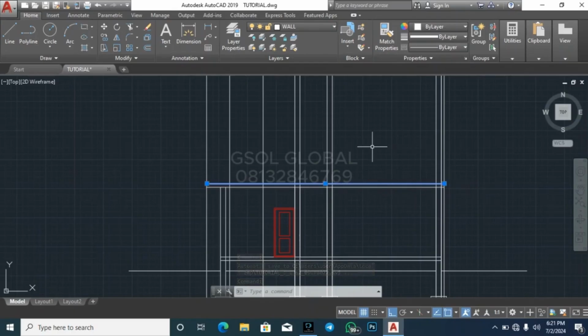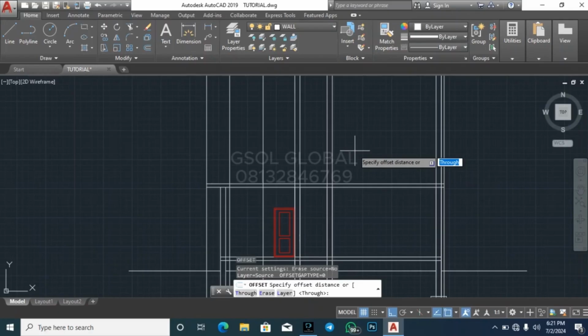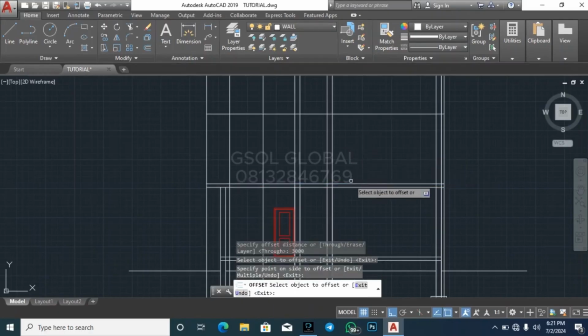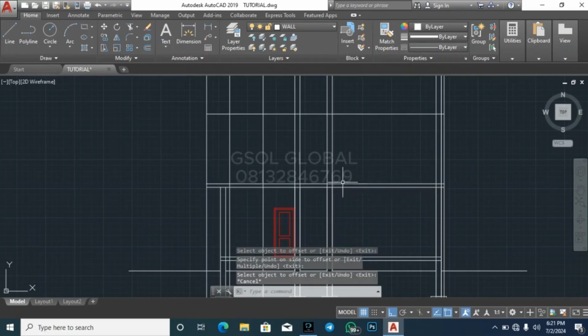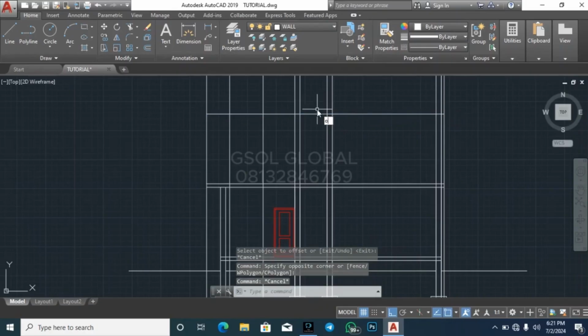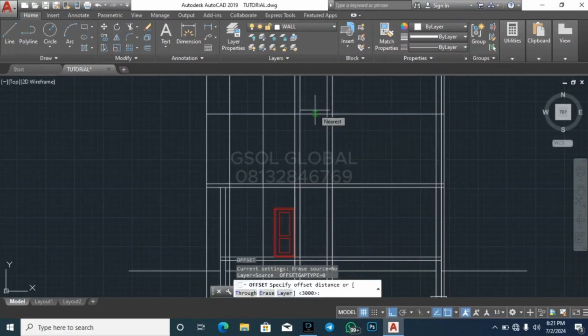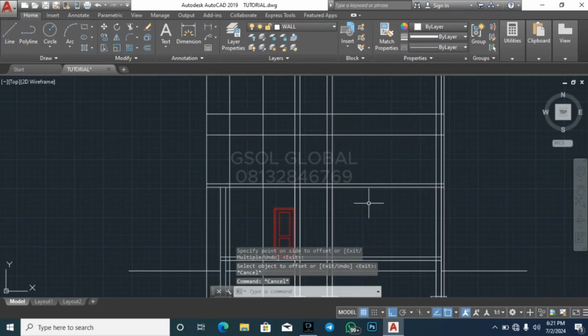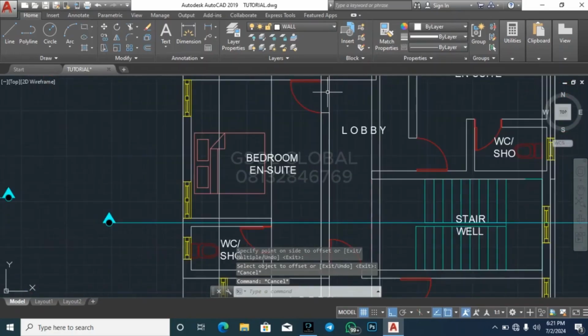So as you can see, we are done with the ground floor section, right? So make an offset of the headroom height, which is what, 3 meters. And then your offset, right? So now, when you are done with this, you're going to make an offset of 900 downwards so that in case you're having any window or door component, you can just insert that ASAP. So like this.